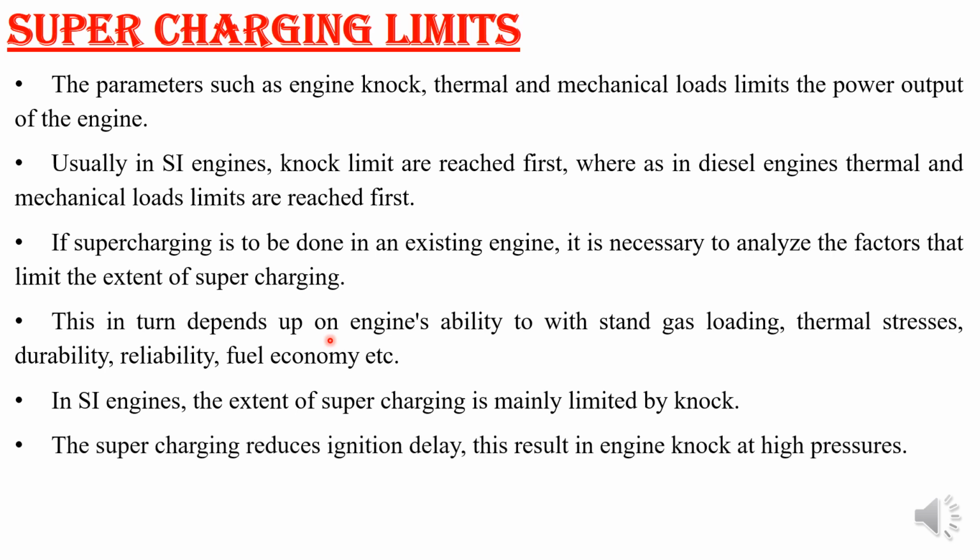Whenever you do supercharging, one important factor: because supercharging supplies more air, it will create turbulence inside the engine. Whenever turbulence is created inside the engine, what will happen? It will reduce the delay period of combustion. You have studied the delay period in the SI engine: once the spark is ignited, it will take some time to initiate combustion. That time is called ignition delay. If that delay period is more in an SI engine, then what will happen?